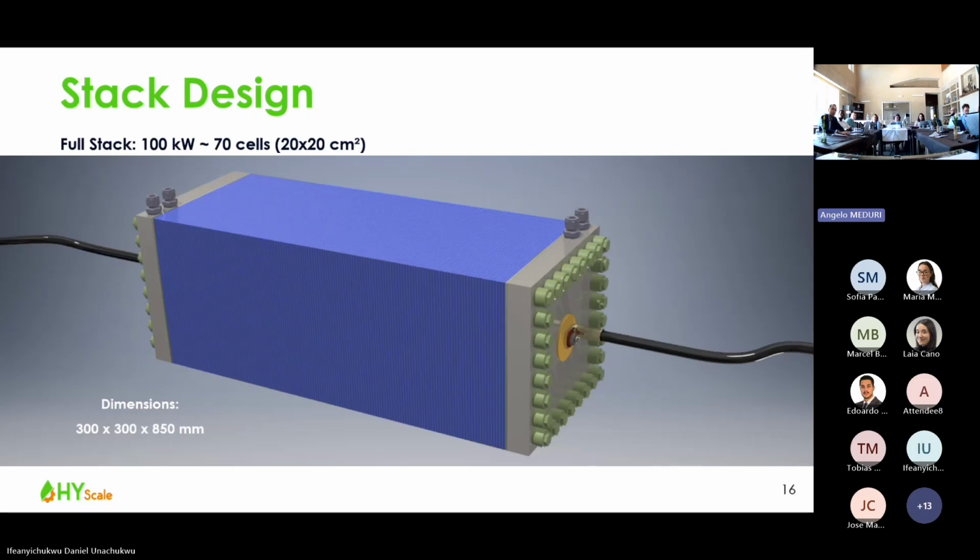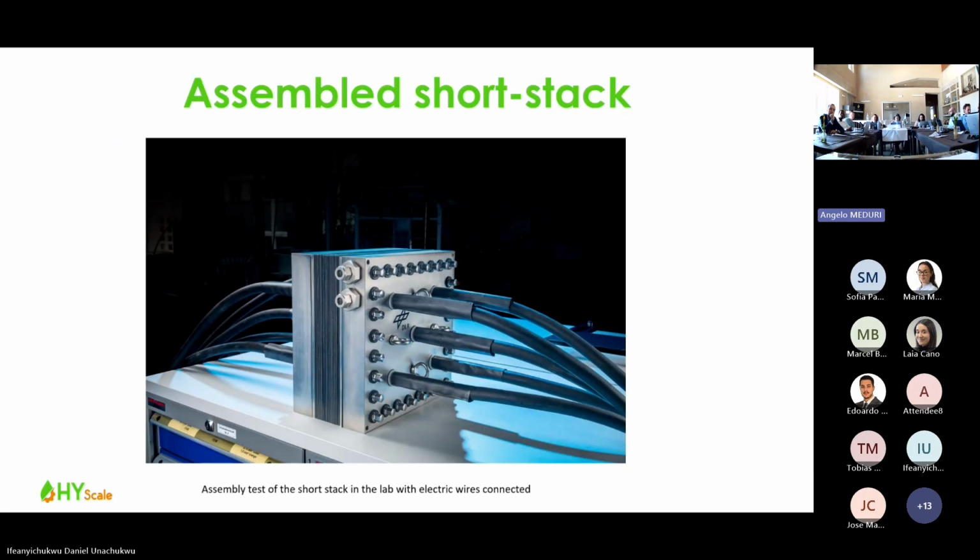For the electrical connections, we decided in the end not to do it like here, where we have the produced short stack with 5 connectors, because the heat generation at 1 kV would be too much when divided into 5. Also the current distribution is better in that orientation.